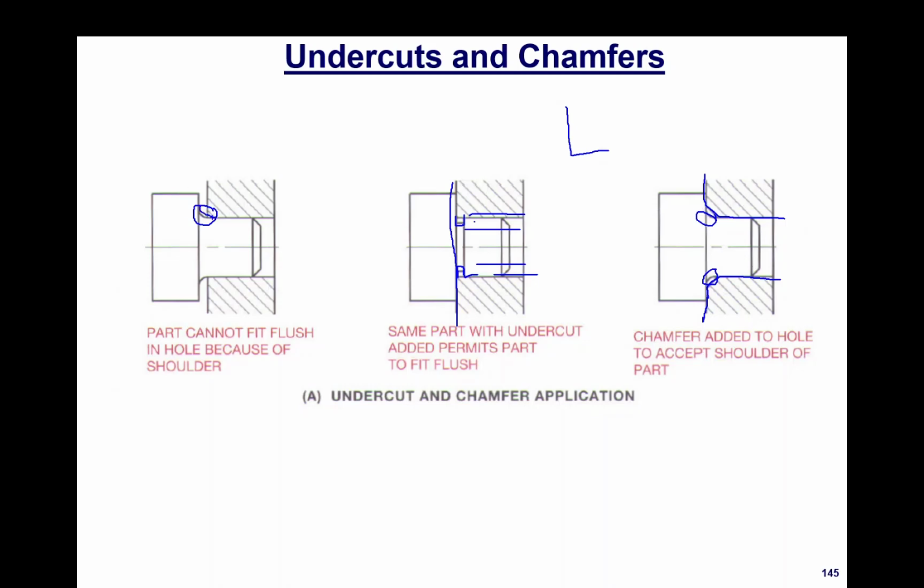If you look at shafts on your car, journals on crankshafts, trailer axle spindles, they all have a radius when we step up or step down the size of the shaft where there's a bearing fit. And the inner race of the bearing will have a taper or a round on it so it can clear this fillet on the shaft. We don't want stress risers in our designs. So these are important features.